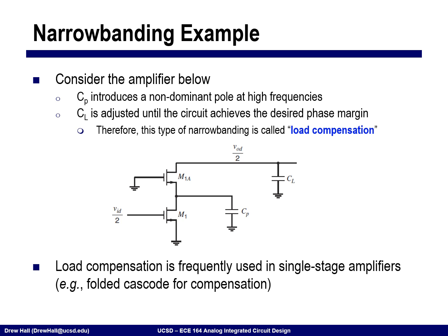So if we look in a little bit more detail at this folded cascode, I'm showing you the bottom half of the half circuit. There would also be some biasing circuits up here. This could be the folded cascode. This could be the telescopic. All of these have the same kind of small signal structure here with slightly different values for gm and ro.